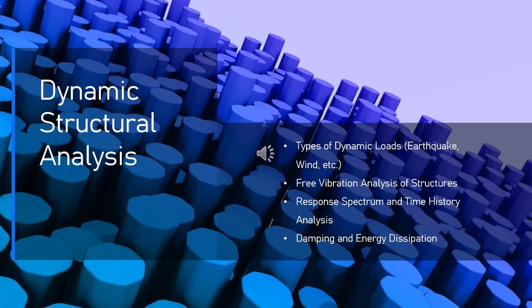Energy dissipation mechanisms. 1. Internal friction. Material damping. In materials, energy dissipation occurs as internal friction between particles or molecules, converting mechanical energy into heat. This is particularly evident in materials undergoing plastic deformation. 2. Frictional damping.